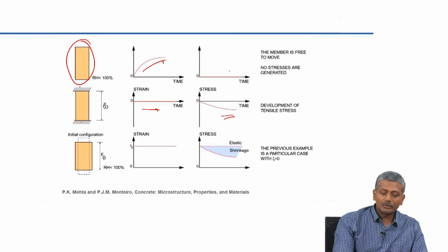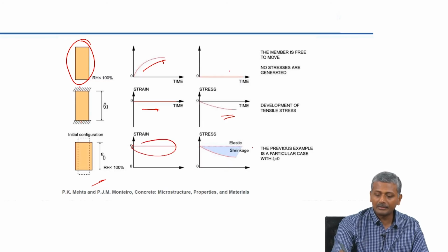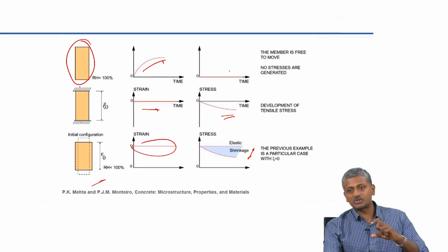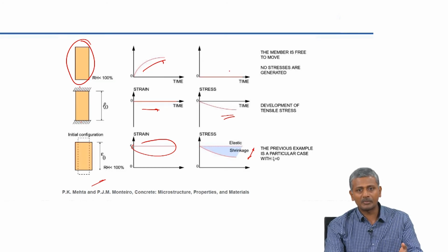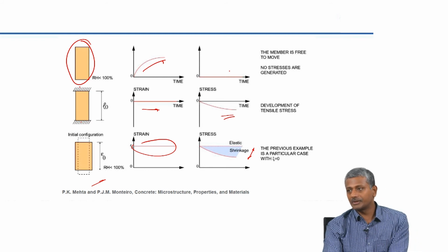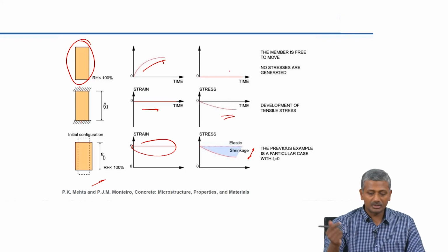Now, in this case, what we have is a constant strain, and the reduction of stress caused because of relaxation as well as shrinkage will be more than what is caused by relaxation alone. So, this is a combination of the relaxation experiment done with drying. Your overall stress reduction is going to be much greater with shrinkage in this case.